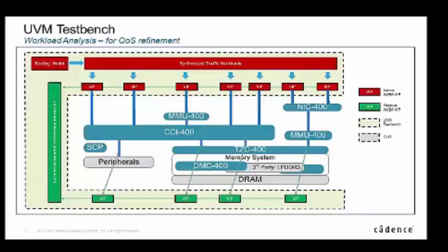There is an enormous number of configuration parameters, especially in commercial IP, because you're trying to produce an IP that satisfies everybody's possible configuration. I know for sure in our IP we have options for configuring command FIFOs, write FIFOs, read FIFOs, hundreds and hundreds of them. The difficult thing is that it's not always clear which are the important ones and which are the non-important ones, and that's something we want to help the users understand. When you get an IP, can you do some characterization of your own and understand which are the important knobs to twiddle, and which aren't?